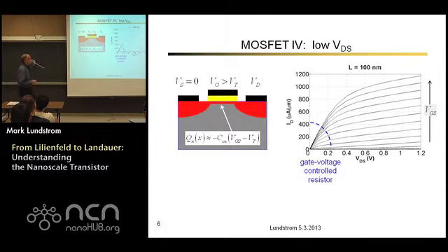So let's look down in that low voltage regime. How do we think about the MOSFET IV characteristics? All right, it's very easy. We apply a gate voltage that's bigger than the threshold voltage. That induces a channel of N-type electrons. We get some negative charge in the channel. Charge is just capacitance times voltage, but we have to have at least the threshold voltage to get any significant charge. So we have that simple relation for the charge in the channel.